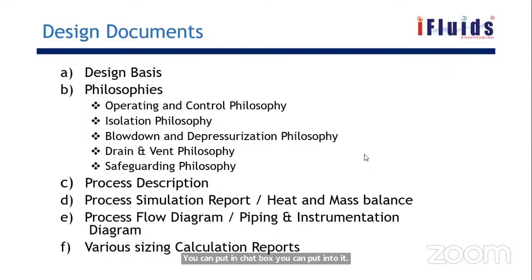In case of fire, people might have heard of boiling liquid expanding vapor explosion. So in case of fire, all are metal only, right? All the metal will get the heat and then go to the next stage. That means it will soften and then finally it will rupture. With the pressurized content inside and the hydrocarbon inside, it will cause an explosion and add fuel to the existing fire.